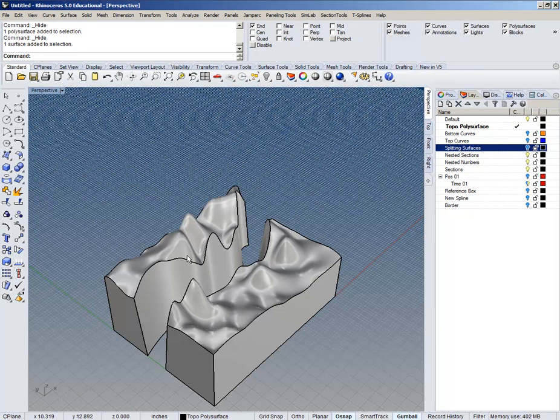So same thing, but remember we did our contour command, we're going to do something similar, but we're going to go in the other direction. We're going to use Section Tools because it's going to give us output, instead of just sliced up sections in 3-dimensional space, it's going to give us the ability to label and lay out our sections for the laser cutter. Section Tools is a free plugin. If you're running Rhino on your PC and you don't have it, you can just Google it. It's free. It's Raja's plugin.